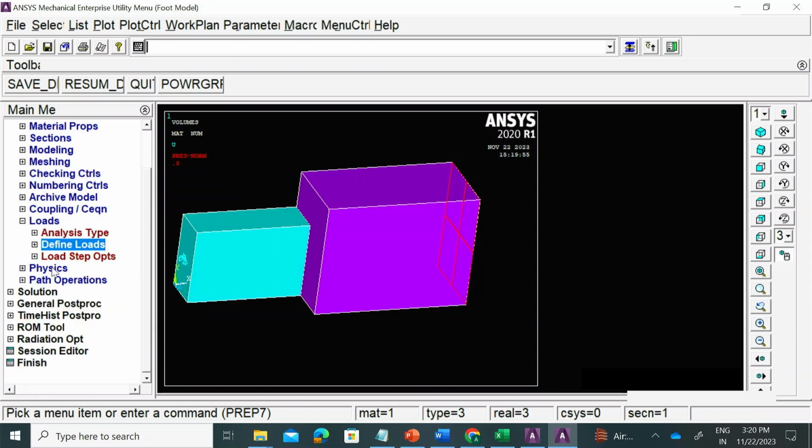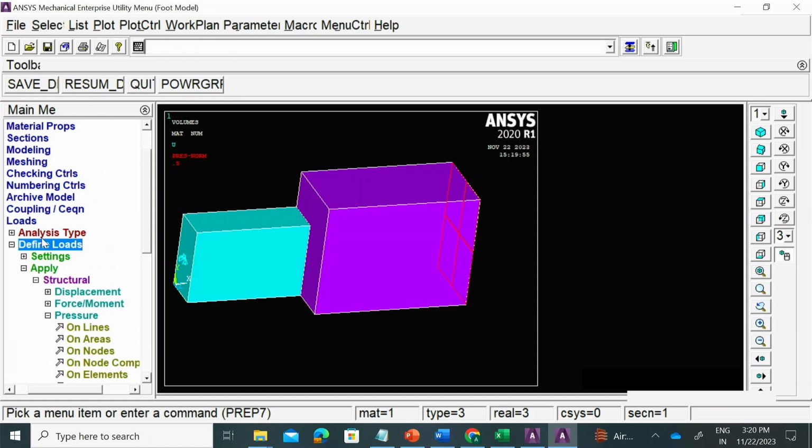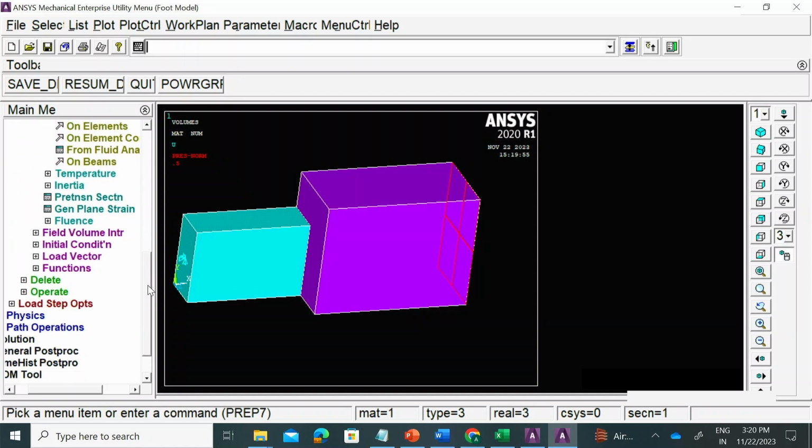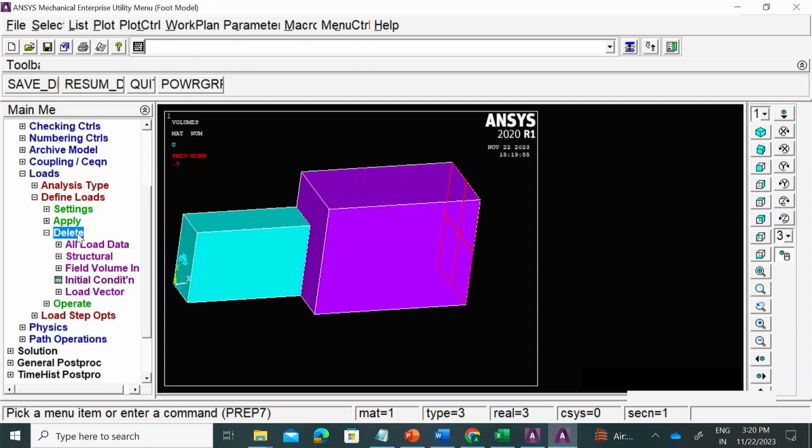So this is the fault detection time. Many a time your solution will not run and you need to be able to figure out why it is not running, and these are the failure analysis things which we do. We want to check the mesh, we want to check the mesh is okay, we want to check the contact pair first in cases of contact pairs. Second is we want to check on the loads. Is the load way too high for the system, so that there is a disassociation going on with the system, like one is penetrating into another or things like that?